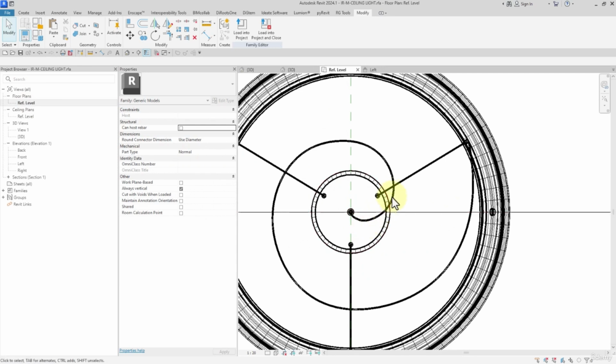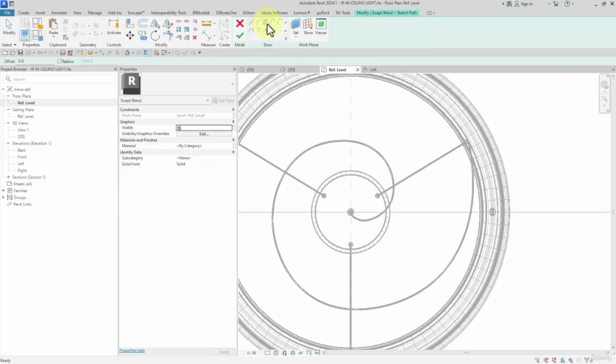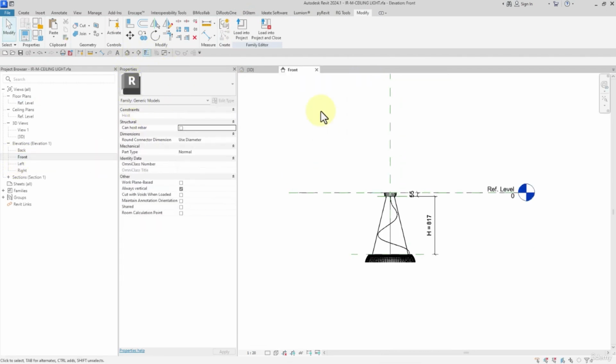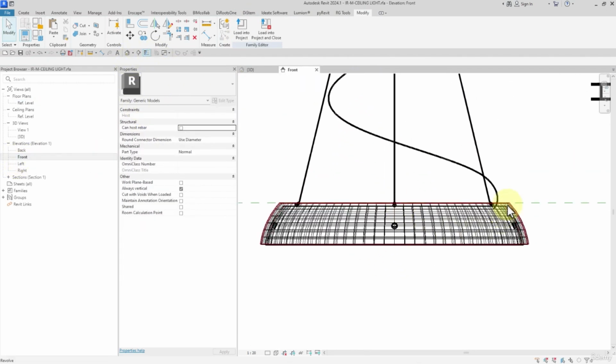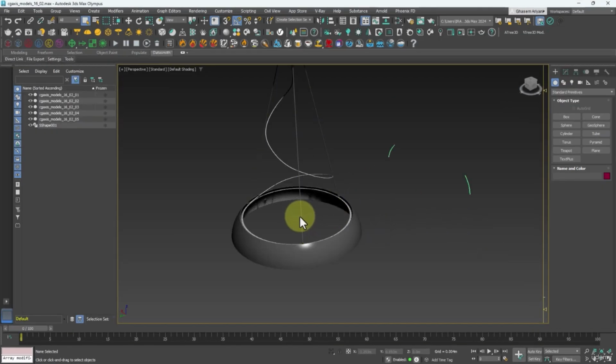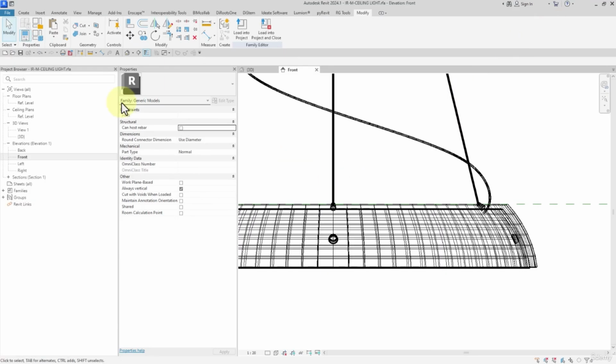Then we get back to the top view for this part. However, here you may find this complicated since we cannot draw something in Z direction, but we can use sweep blend. Let's see. Cancel. Firstly, I open the front view, and then I want to, let me see. As you can see, it starts from the edge. So let me open the plan view, front.